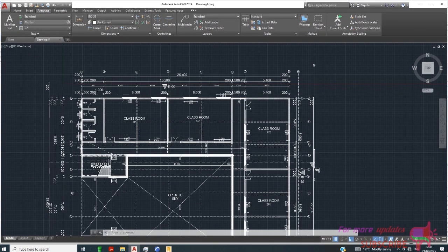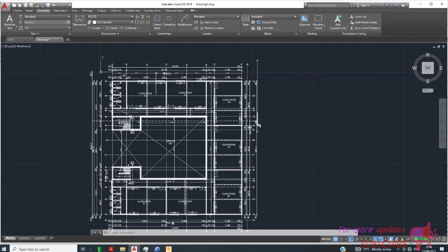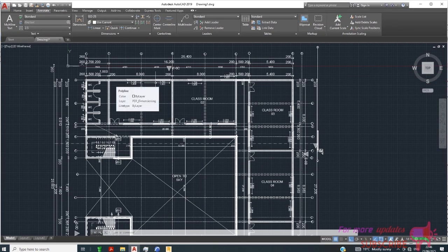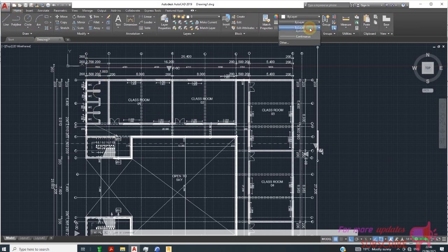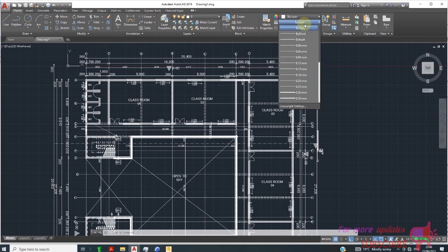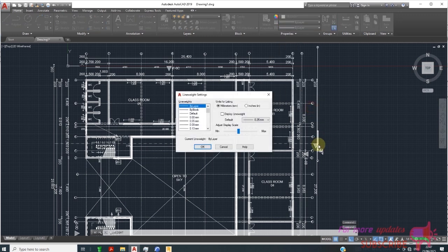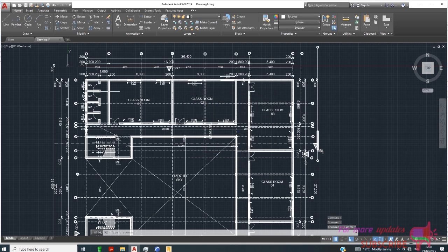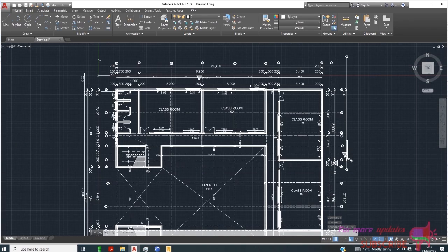So as it does so, I want to explain another concept, that is designing halfway the model. So before I do that, I'm going to show you something. So let me first go to this particular layer. I'll go to settings. Let me show you something. Display lightweight, and click OK. Okay, then I want to just activate a polyline, change the color of my polyline to red.